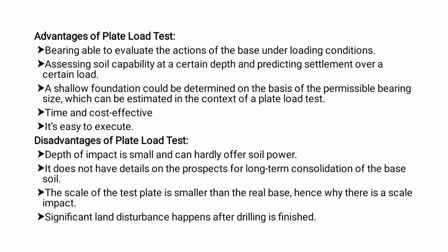Disadvantages of the plate load test: the depth of impact is small, the scale of the test plate is smaller than the real base, and significant land disturbance happens after drilling is finished. So in this video we saw the standard penetration test, cone penetration test and plate test. Thank you.